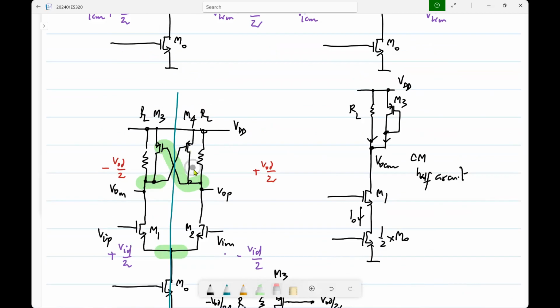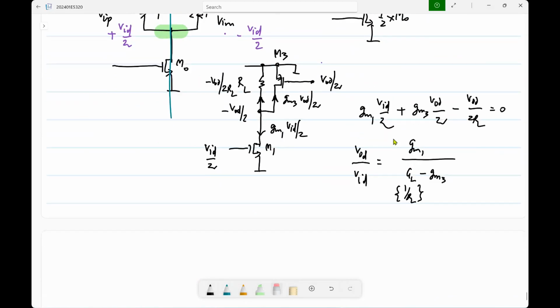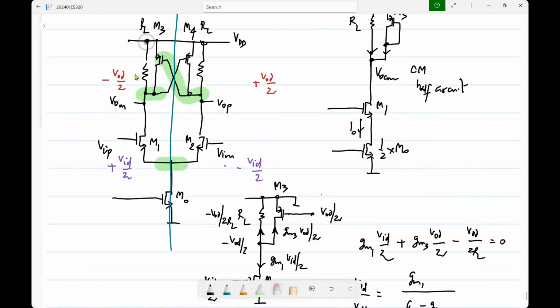Okay. So essentially this cross-coupled pair behaves like a negative resistance. I'll show this. In fact, the assignment had things like this, right? You were asked to calculate the impedance. I don't know if the cross-coupled one was part of it. Was it there? Yeah. So you must have got the negative resistance as that value. Okay. So essentially, you have a positive conductance GL and a negative conductance GM3 across it. So the conductance actually decreases by putting a positive and negative conductance in parallel, or you can make it decrease. So that's one way to enhance the gain.